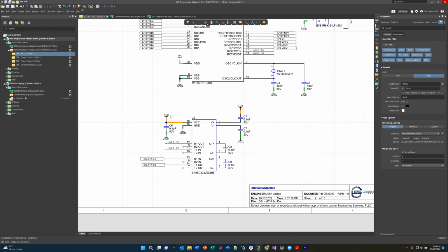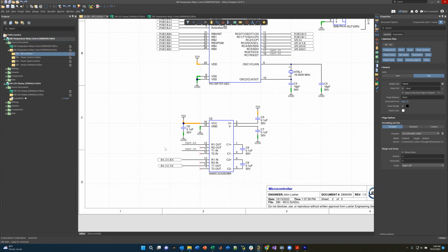I've talked about it, I think, in the previous lectures on microcontrollers. These talk at TTL levels, basically 5 volts, transistor-transistor logic. But that is not how RS-232 works. RS-232 is an electrical standard for UARTs, and RS-232 is plus or minus 12 volts. So on the actual wire, a 1 and a 0 is either plus 12 or minus 12.